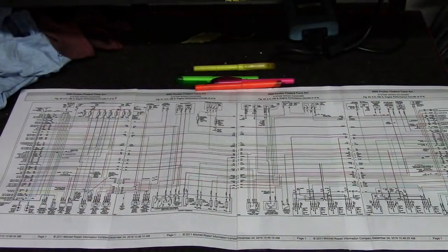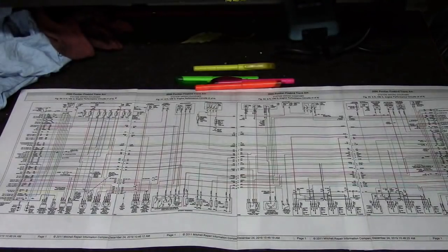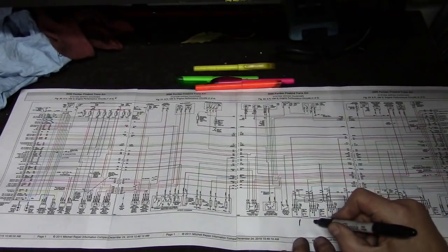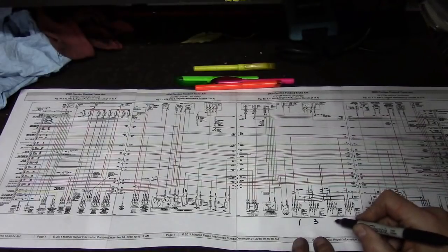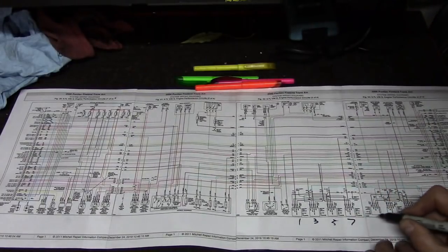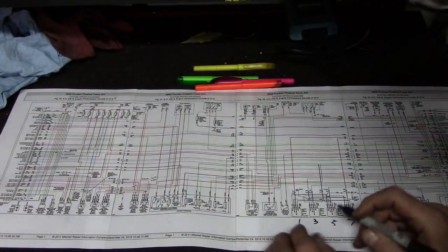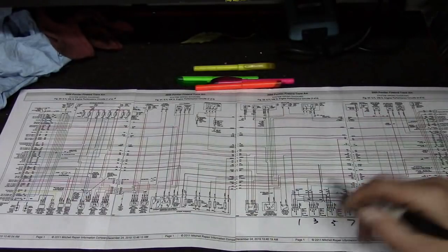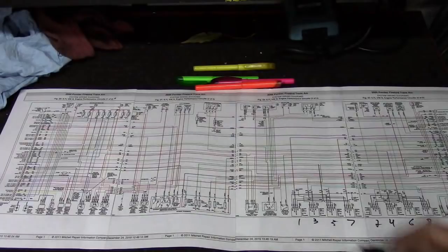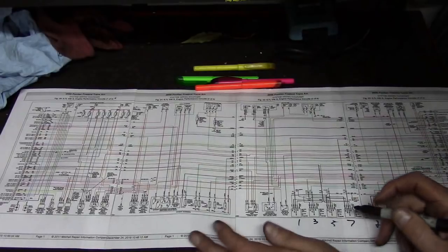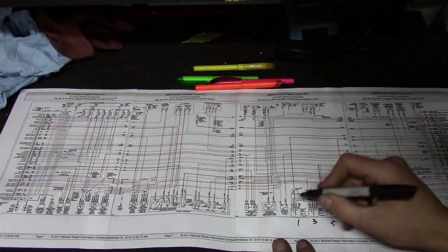What I want to do is start again with the load. And I realize that you guys are not going to be able to read this. To be honest with you, neither can I. But here are our ignition coils. There's 1, 3, 5, 7, and then this is going to be 2, 4, 6, and 8 over here. So there's our ignition modules. What did I tell you? They don't show the transistors in the ignition module. All it is is just a box, and it says ignition coil number 1. That's all. So our diagram is actually quite a bit more accurate.